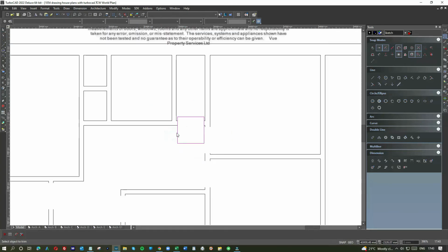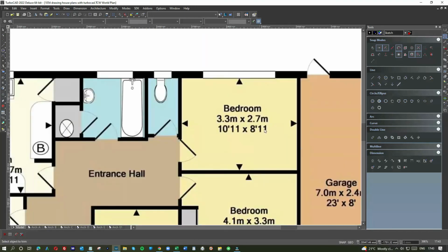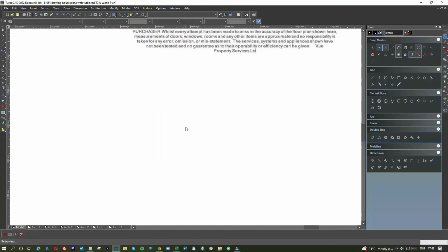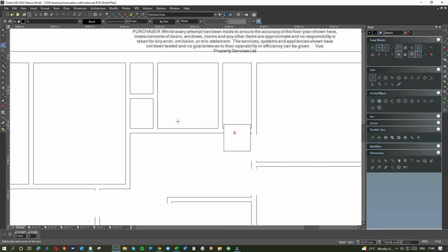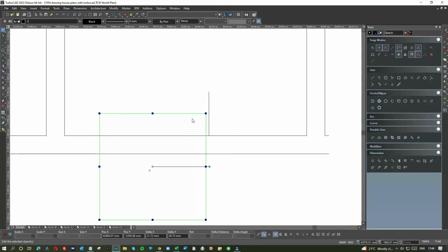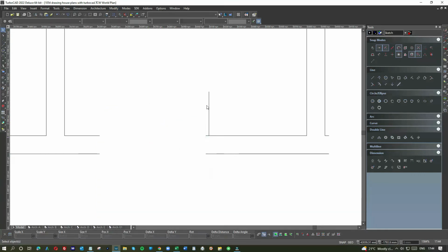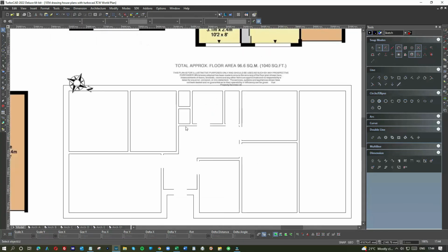Let's see when I put the doors in. They'll go in very quick. So now we got a bathtub going in there on the back of the wall. So what's the size of a bathtub, anybody? 700 standard. Tab 700. So we don't want the door going in at the end of the bath. So we're going to put the door and allow for the door to open. Modify. Object trim. So there's generally a reason why things are where they are. But not always. Sometimes it's just pure incompetence.